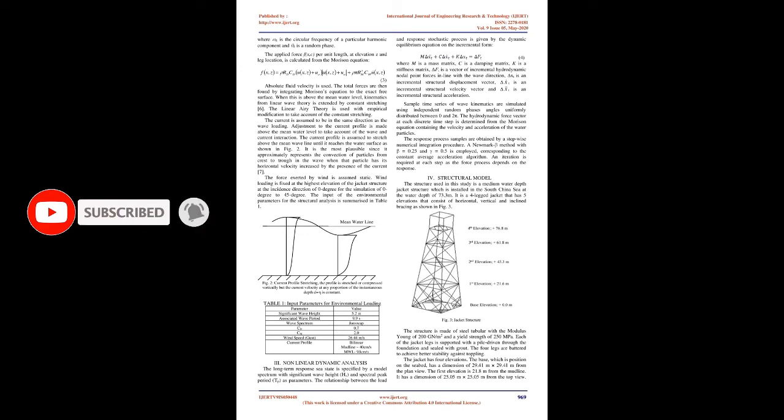Ft is a vector of incremental hydrodynamic nodal point forces in line with the wave direction. Xt is an incremental structural displacement vector. Ẋt is an incremental structural velocity vector and Ẍt is an incremental structural acceleration.